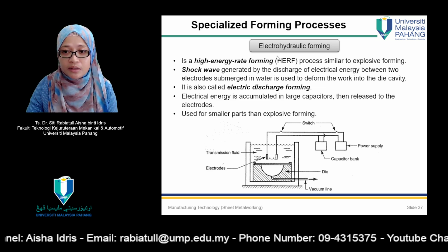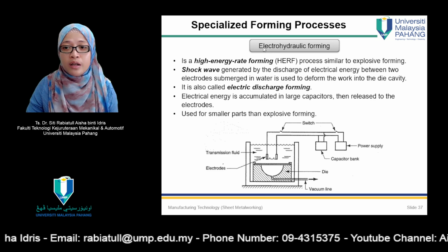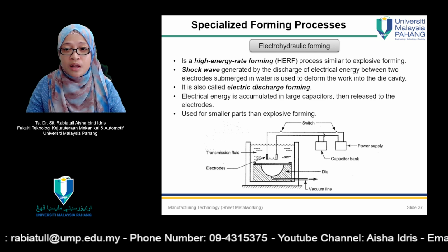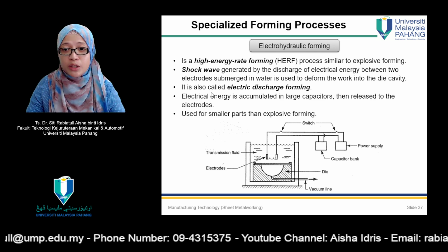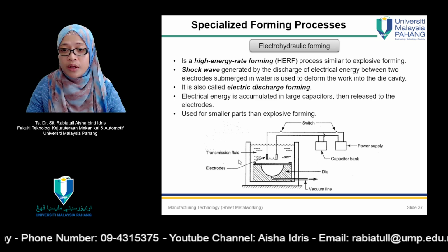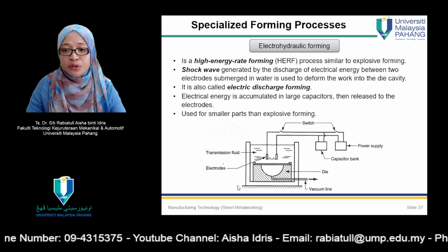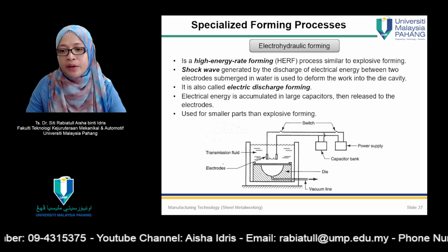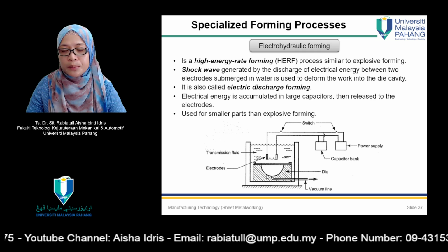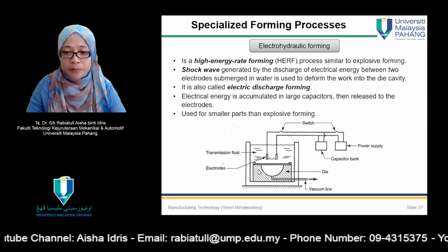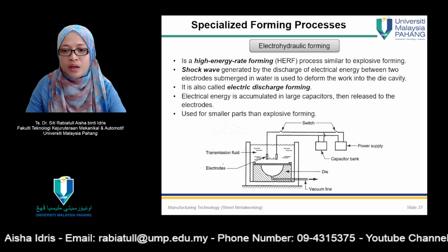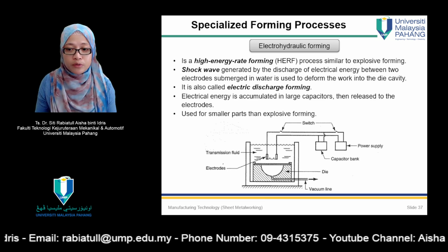And other than that, there's also electrohydraulic forming. Well, the process is actually more or less the same as in explosive forming, and it uses high energy rate forming. This one is also called EDF, electric discharge forming. As compared to explosive forming, electrohydraulic forming is used to form smaller parts.